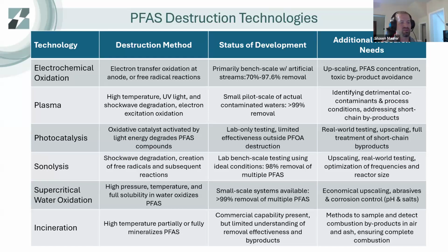These do have an impact on pH, so that's part of the research is optimizing the process, either through using additives to control pH, and how to address abrasives, things like that come out in the process, so that it can be maintained long term and isn't degrading just through its own process of creating these salts, and other co-contaminants that move through the system with PFAS that can degrade the internal materials.